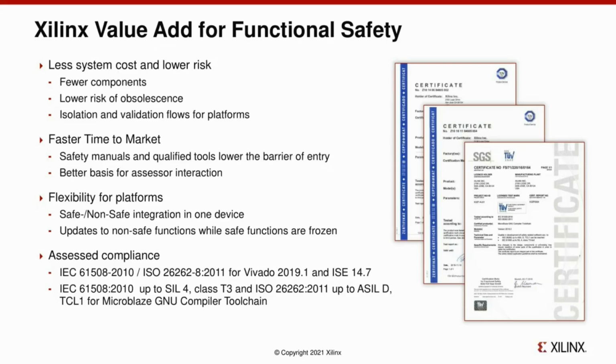What is also important to note is that Xilinx tools, Vivado and Vitis, are functional safety certified for IEC 61508 and ISO 26262 on the tool side. And on the device side, we have a soft processor called MicroBlaze. The MicroBlaze GNU compiler toolchain itself is certified under ISO 26262. So we take functional safety very seriously, and we offer a lot of support for functional safety, both for the SIL 3 and SIL 4 standards.